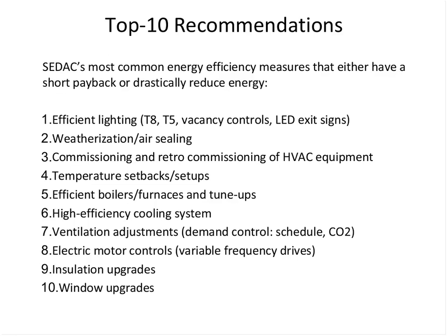Ventilation adjustments. At the very least, schedule the ventilation in the building with a time clock or something, or do demand control ventilation. Very great savings associated with ventilation. It is quite expensive, and it's only needed for when people are in the building. Electric motor controls, VFDs, variable frequency drives, insulation upgrades, and window upgrades.